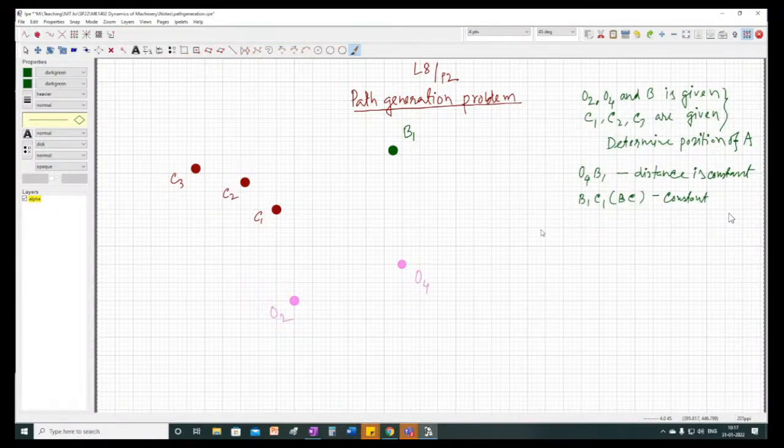Okay. So using these two pieces of information, we can find out B2 and B3. How to find this? Can you tell me, somebody? B2 and B3? We will cut two arcs, like the length of BC from C and O4B length from O. Anyone else? Hello?